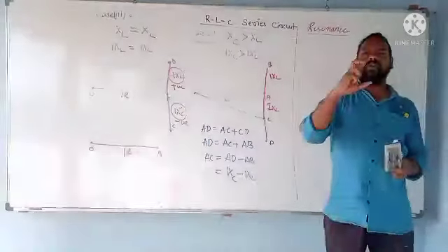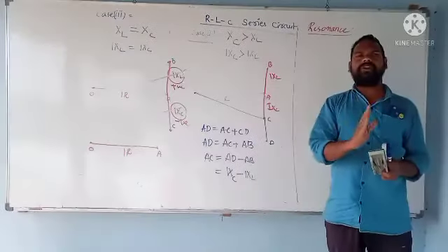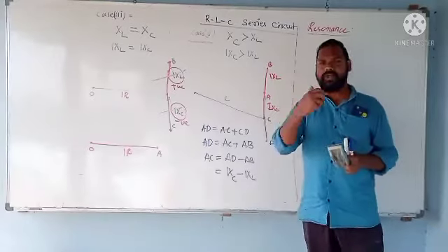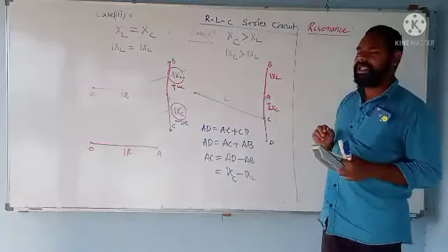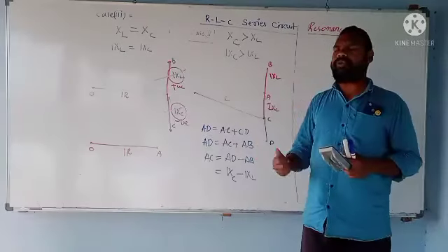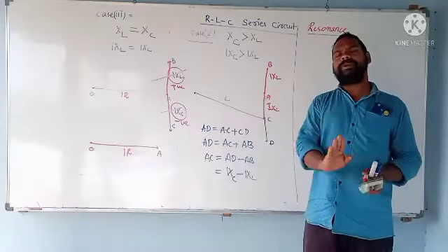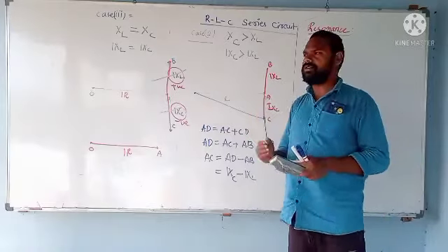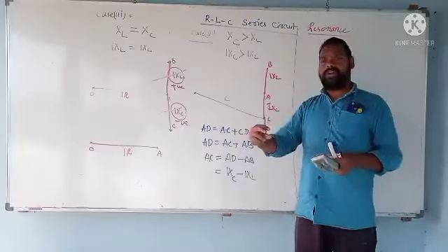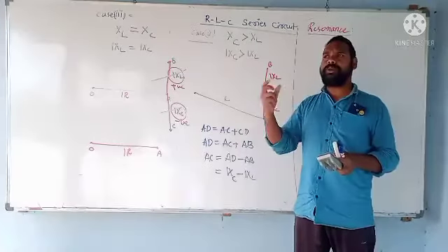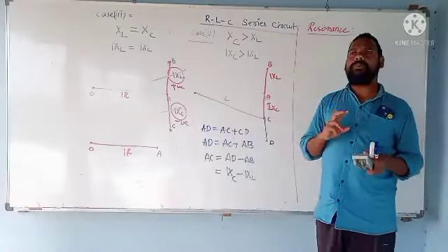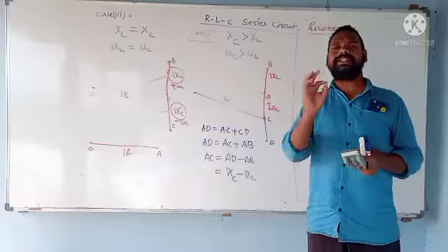Whenever you are applying capacitive loads, inductive loads and resistive loads at home, the distribution companies, whoever is sending the power to you, make the compensation of both the reactances. If capacitive reactance is dominating the inductive, then inductors are going to be connected to compensate the capacitance. When inductors are dominating the capacitance, in that case capacitance is going to be used for the compensation of the XL term. So it means the distribution companies always try to make the circuit a resistive circuit.